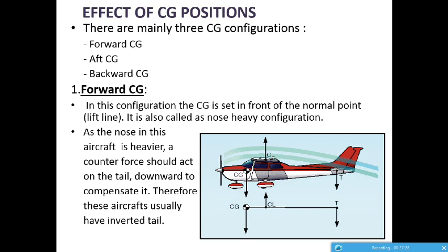If it reduces its speed, then the aircraft results in a stall. And there are also some pitching problems, because since it's nose heavy, landing becomes a difficult task. It always tends to dive into the landing field, and you have some pitching problems.